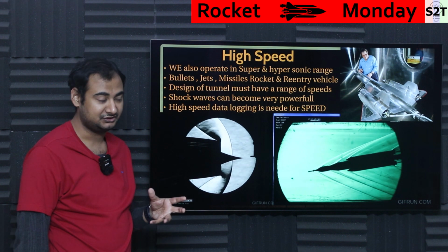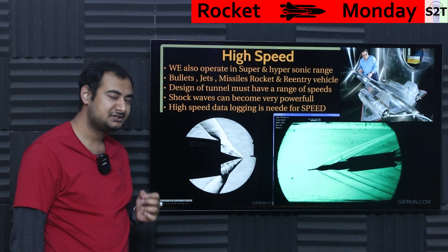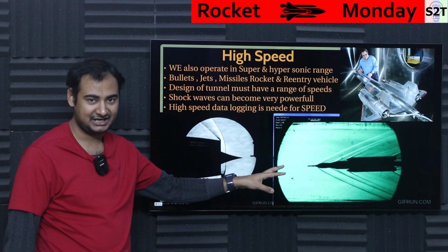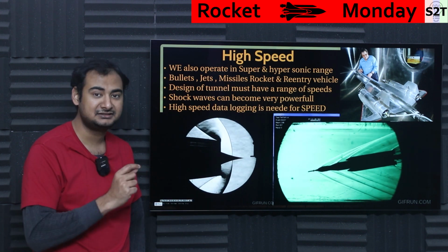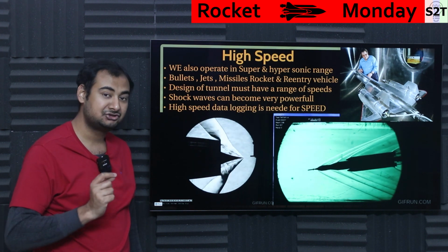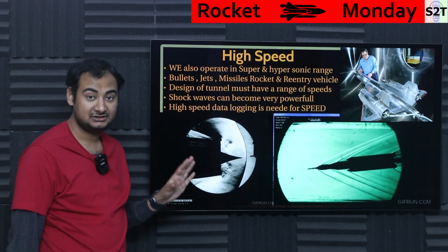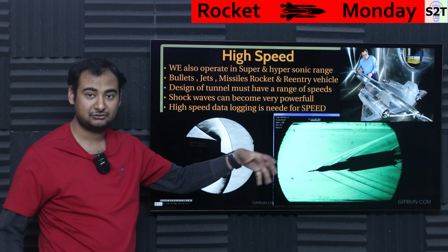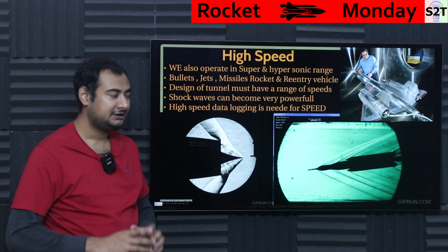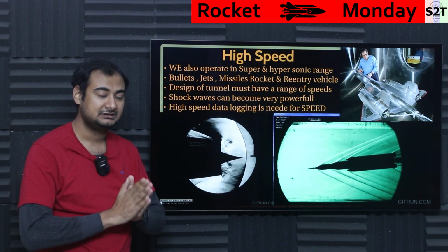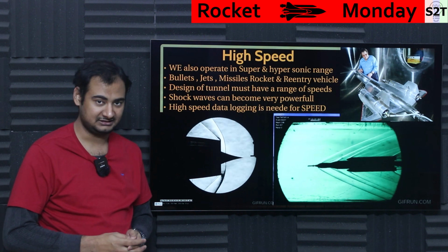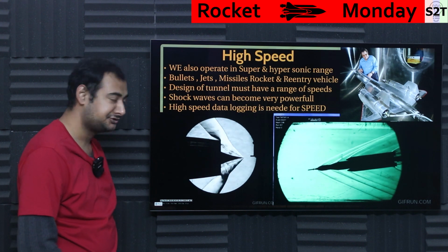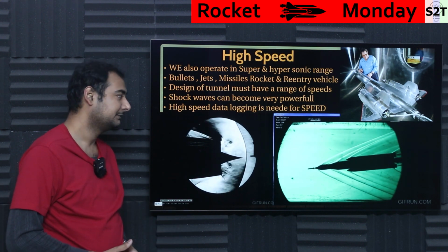And whenever you are talking about supersonic speed, you do have to understand shock waves. These things become destructive, not only to your models. If your model is not built properly, it will shatter. And be mindful, at this point you're going to fling things at Mach 2. It can punch through walls at that point. So it's a very serious thing that you have to understand shock waves. And not to mention, even if your model is like, I'm God, I can withstand it, the shock wave could cause damage to other things. You have to take that into account. Shockwaves are serious things. It's not a laughing matter, especially if you have acrylic windows. You have to be very mindful of that. Bad shockwave, boom. So you have to understand it.